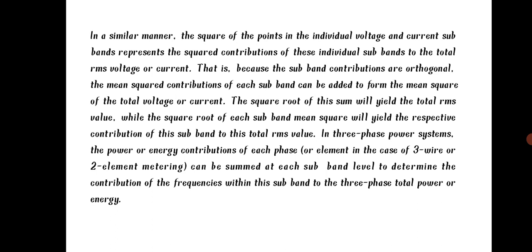In the three-phase power system, the power or energy contribution of each phase, or elements in the case of three-wire or two-element metering, can be summed by each subband level to determine the contribution of the frequencies within this subband to the three-phase total power or energy.